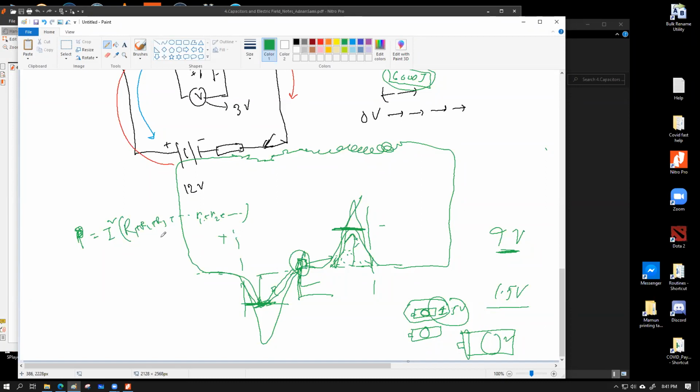So essentially speaking, if you can reduce your current value, your loss should become less compared to your resistance because there is a square over here. Which means if you can operate a certain voltage, think about it, V equals IR, right? V equals IR. If you want to reduce the current in a circuit, you either have to increase the resistance for a given voltage or you have to reduce the voltage.